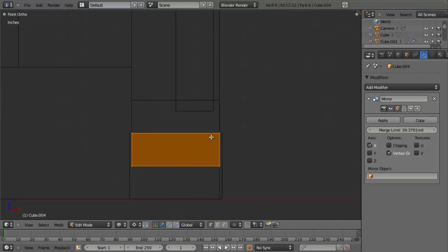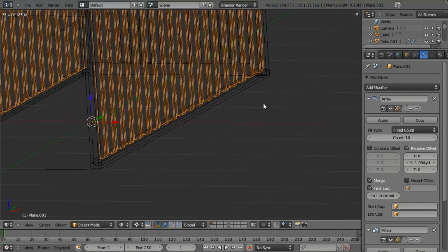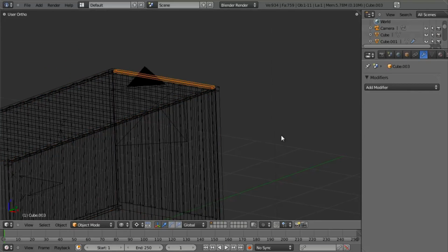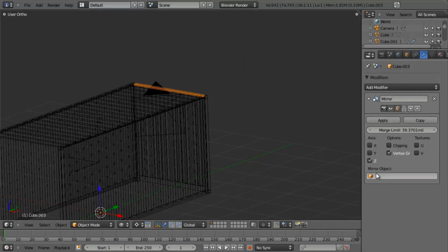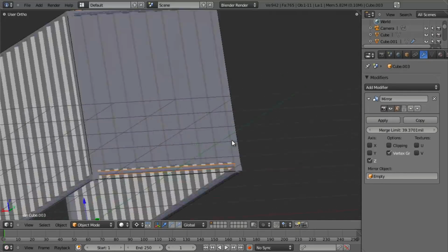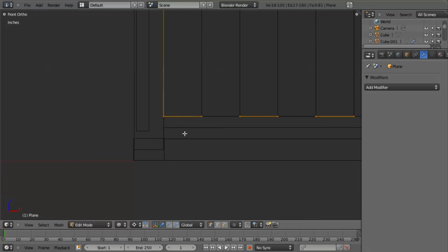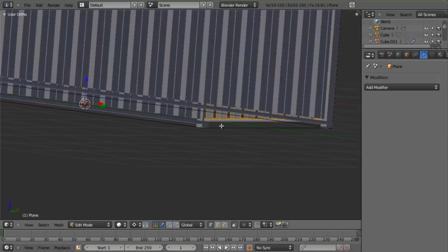And then what I'm going to do is first, if we look at this, oh, and actually I did this wrong. What we want to do is we only want this side beam to be along the back. So let's remove the Z empty there, select this back one here, and add in the mirror modifier, which will then disable the x-axis, enable the Z, and mirror it across that empty. And you can see we need to bring this back wall down. So we'll select it, pull it down along the Z-axis to right there.